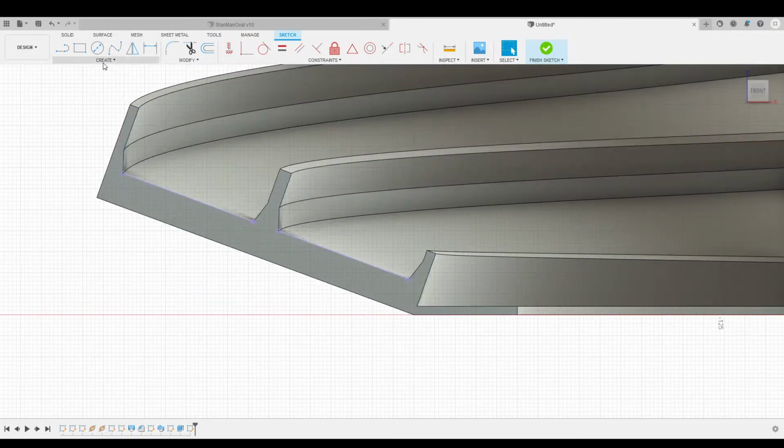So now we're actually going to create a point. And that point, I guess I can make it a construction point. That point on here, so right now we have this X. Well, at some point, no pun intended, there's going to be a triangle, and that's telling us that we're at a midpoint. So we're going to create a point at the midpoint for both of these. Okay, so now we got 2 midpoints. We can leave the construction.